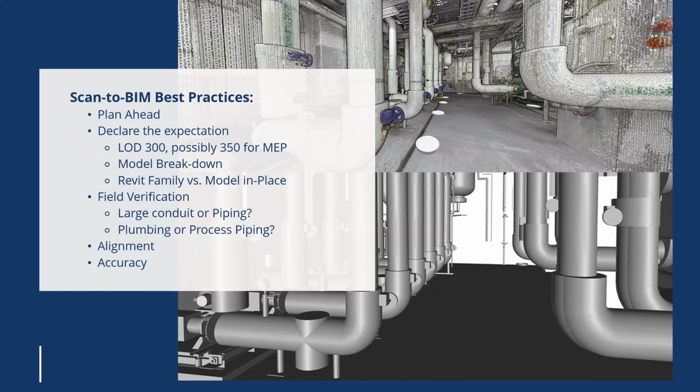First is to plan ahead. Depending on the scope, it could take a couple days or even a week for the scan, and then maybe several weeks to complete all the scan-to-BIM models. Plan it ahead to make sure all the required information is available before scan-to-BIM starts, and make sure there is enough time for scan-to-BIM development.